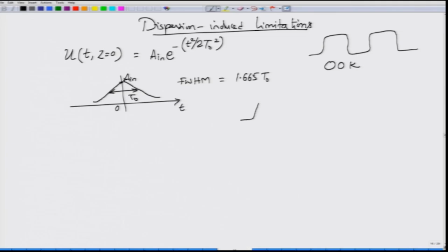Of course, what you launch is a sequence of optical pulses. Here the bit is 1, bit is 0, bit is 1. Sometimes right after the first bit you are going to get a 1 here, indicating that these two time slots, which are very close and characterized by having the same bit, are more likely to suffer from intersymbol interference than these two bits, because this can be allowed to expand a little bit.